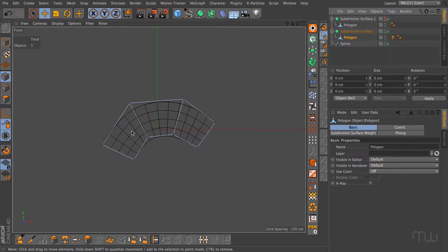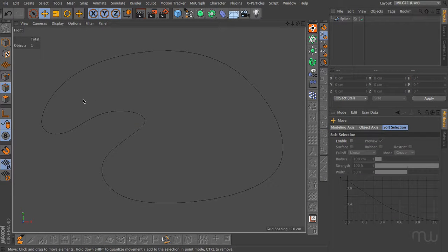Whereas if you start quite low poly, it's a lot easier to fill in holes and gaps and resolve to quads because you don't have to deal with such a high poly count. Now, one situation where this kind of thing will change is when you have varying degrees of curvature. So a good example of this varying degree of curvature would be our spline shape that we saw in the first video. And you can see we have these very broad curves around this area.